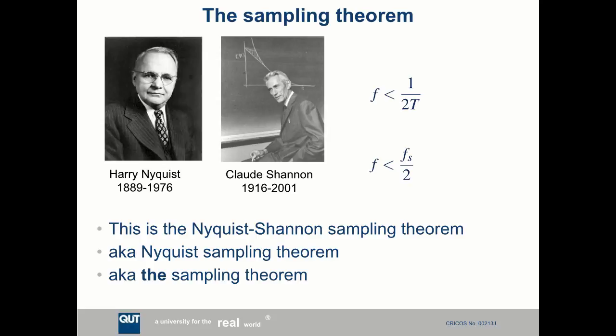So if I'm sampling at 100 hertz, in the input there can be no frequency above 50 hertz. If there are frequencies above 50 hertz, they'll come back, but they'll look like a different frequency. If there was 51 hertz there, it would come back and look like 1 hertz. Yeah? So a very high frequency comes back and looks like something low, and that would be confusing.